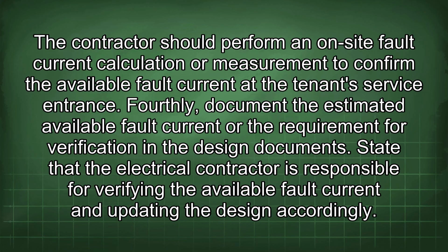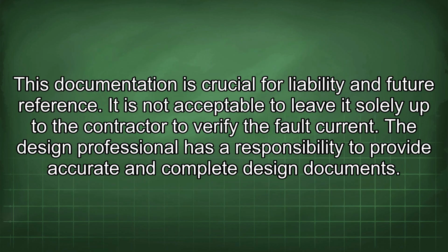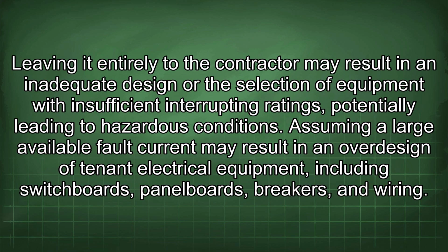State that the electrical contractor is responsible for verifying the available fault current and updating the design accordingly. This documentation is crucial for liability and future reference. It is not acceptable to leave it solely up to the contractor to verify the fault current. The design professional has a responsibility to provide accurate and complete design documents. Leaving it entirely to the contractor may result in an inadequate design or the selection of equipment with insufficient interrupting ratings, potentially leading to hazardous conditions.